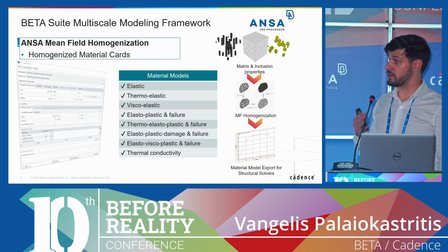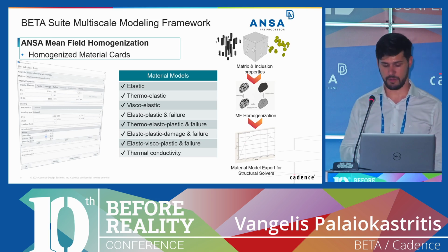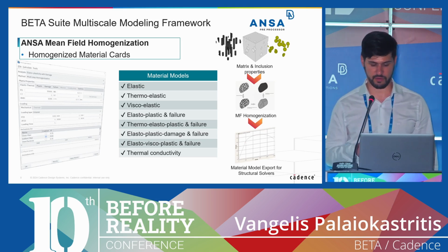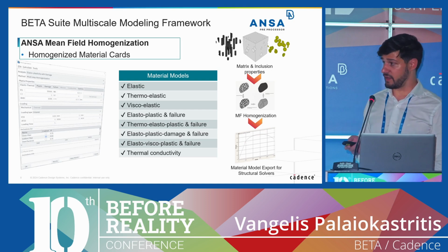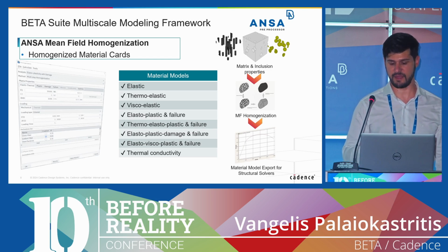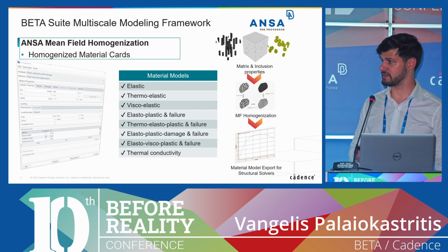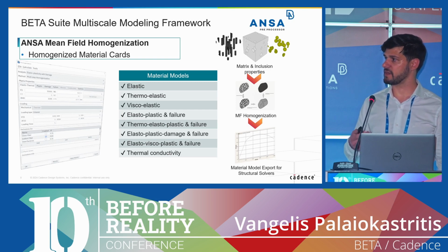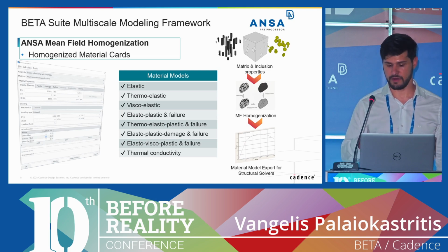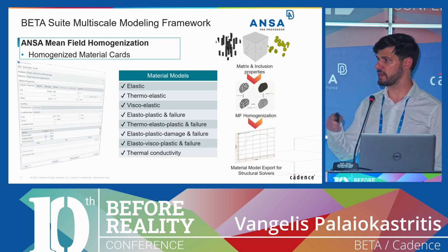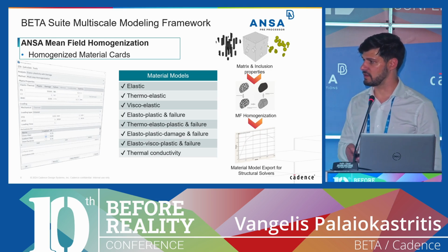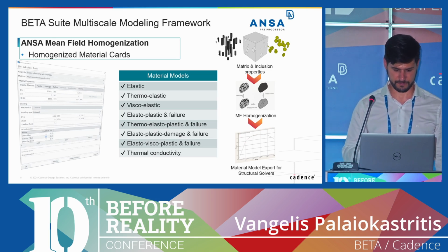The tool will create the material cards for all supported structural solvers, and it is a useful tool at the early stage of the process of material design, due to the fact that it gives the result instantly. So these are semi-analytical micromechanics, so we have instant homogenized properties.